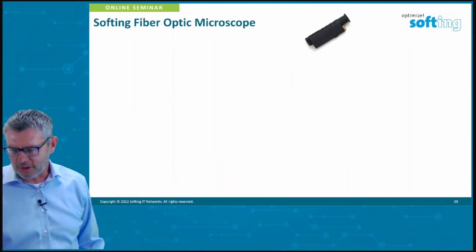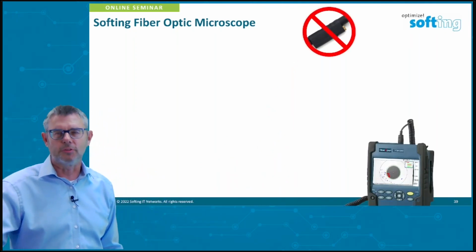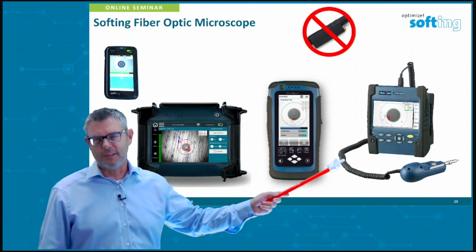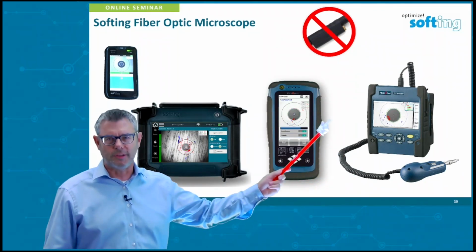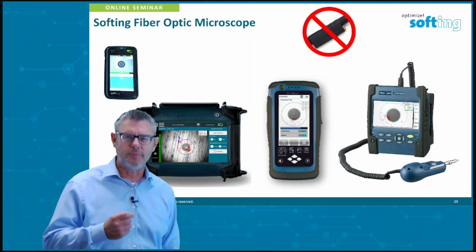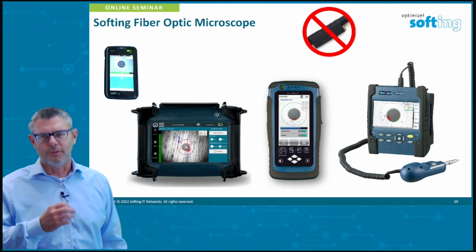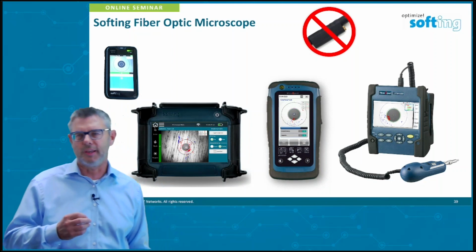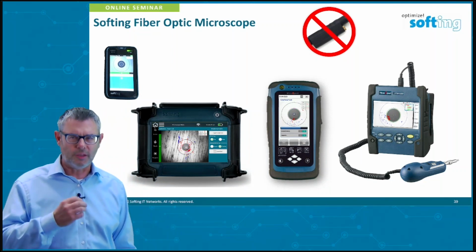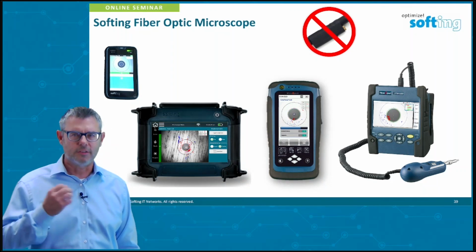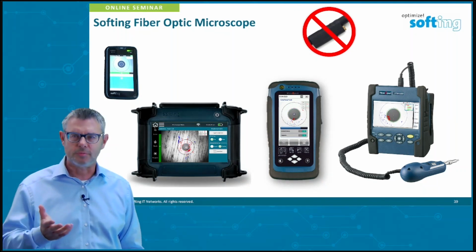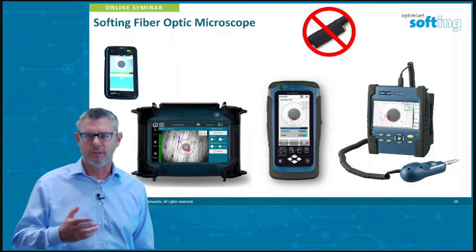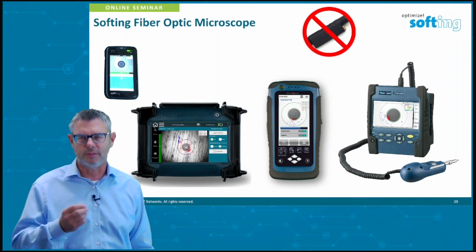When we are talking about checking the quality of the fiber, we are talking about using an electronic automated microscope. You see here in the picture, it's attached to the OTDR and gives you this screen. And what is happening in the instrument? The instrument is automatically analyzing the quality of the picture, the quality of the end connector. And there's a standard, and the standard is used to give you a clear statement. Is this connector good enough to be connected or not? If not, either you clean it properly, or if you can't clean it anymore, you have to swap it, you have to change it. Never ever connect two connectors where at minimum one of the two connectors is dirty or defective. It will definitely break maybe the other one as well, or make it dirty as well.